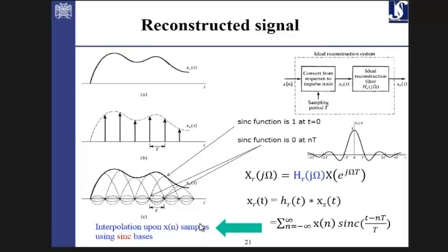What really happens is that this sinc function is actually summed up with shifted versions of itself. So for every sample, you have one sinc function that is placed on that sample, and then it's summed up with the shifted versions of the previous samples. And this is the graphical representation of that.